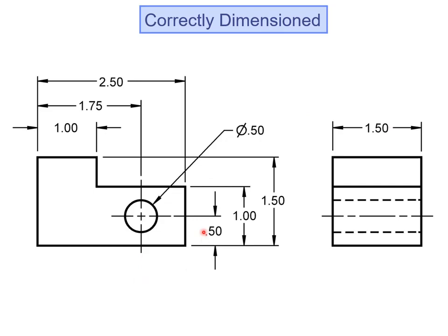Also, since we're dealing with inches, we don't put a 0 in front of the decimal point. If it was millimeters, then we would place a 0 in front of the decimal point. So by removing the 0, we're telling whoever's looking at the drawing that this is in inches. We have the diameter symbol, but not a 0 in front of the decimal point. So this is with any dimensions lower than 1. Drop the 0, and this is only .4 inches.